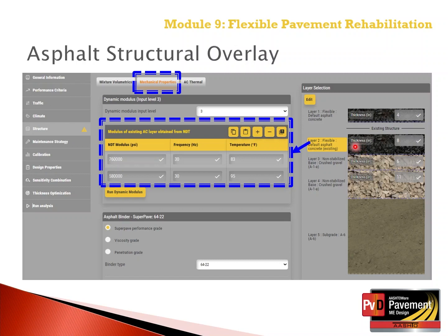Back-calculated different moduli or combinations are combined into one layer, but treated as two in the Pavement ME software. So typically, we're only going to back calculate for one asphalt layer regarding the original construction versus an existing overlay.